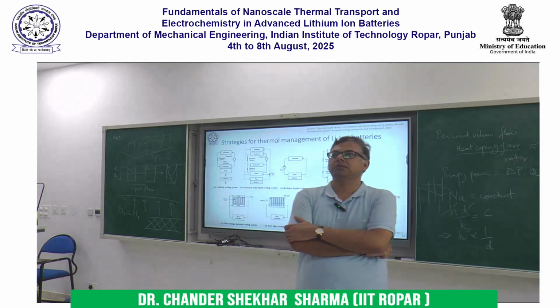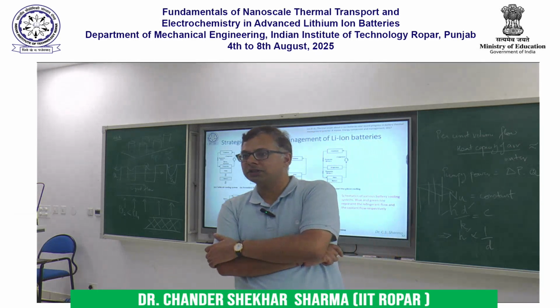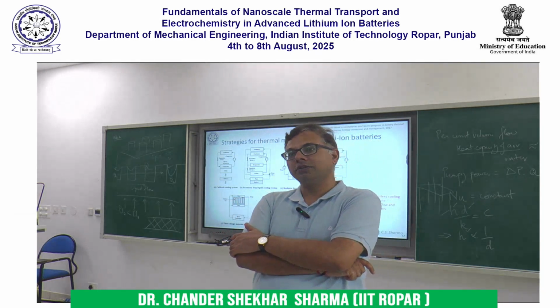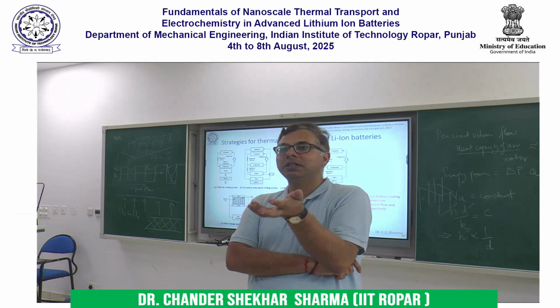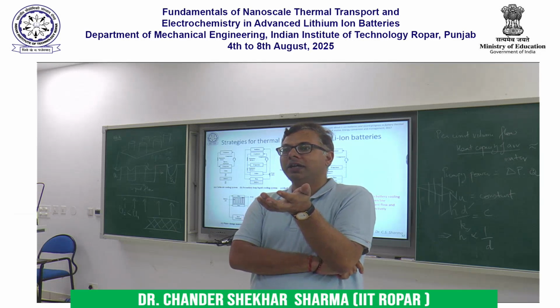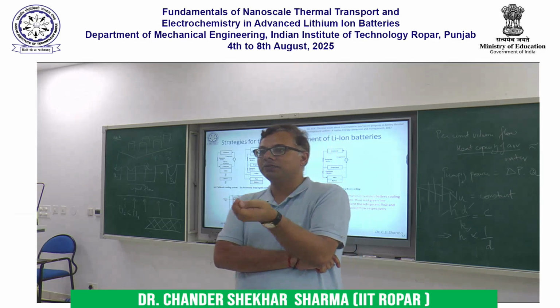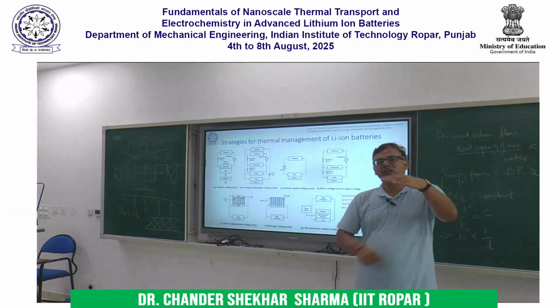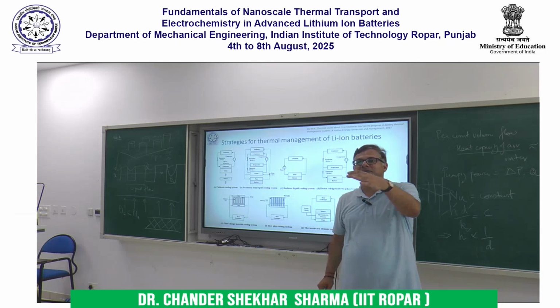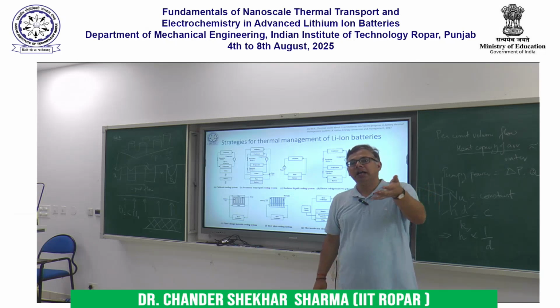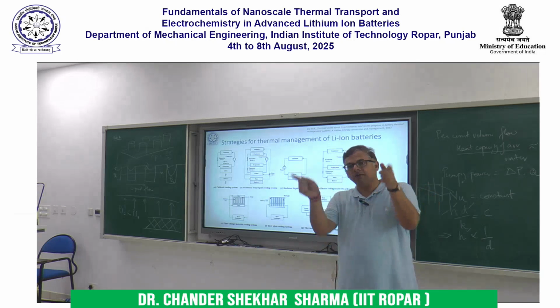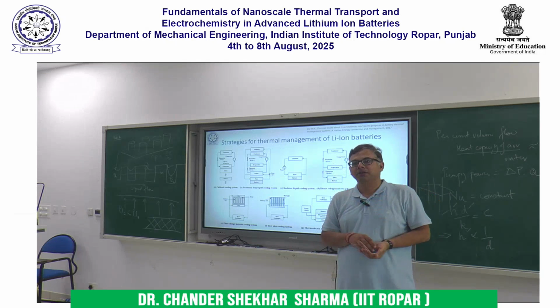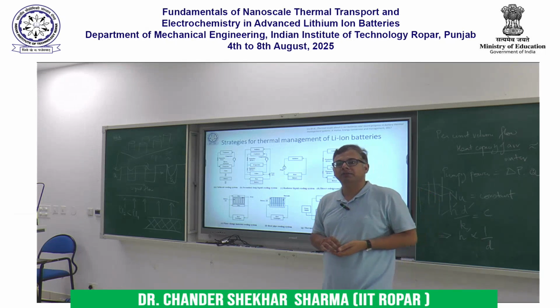So the dry out heat flux will also depend upon how much fluid is there inside, and that is why whenever a new heat pipe is designed, it is tested at different charging ratio. So charging ratio means the amount of the liquid added divided by the internal volume of the heat pipe. So that is also strongly a parameter.